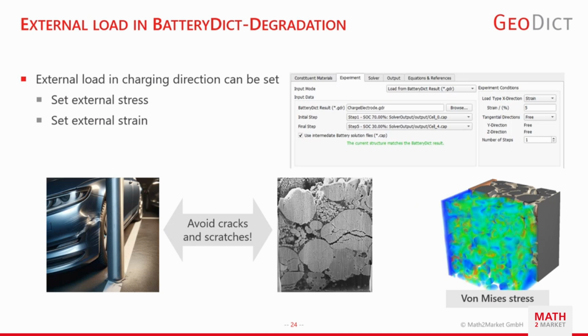And very similar it is also for the battery, because with every charging and discharging, you introduce lithium ions into the active material and you release it again. And all this insertion of lithium ions will lead to an expansion of the volume and to a shrinkage. And if you do fast charging, then even this mechanical stress is larger on the active material.